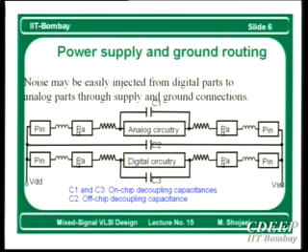We assume that we have designed the board in such a way that the VDD line is quite a perfect line, a wide line, and straight. It doesn't have as such inductive effect. Therefore, the effective inductance will be the wire bond inductance. If we have an inductor here, then actually the PCB design is not correct. There are many things also associated with the design of PCB.